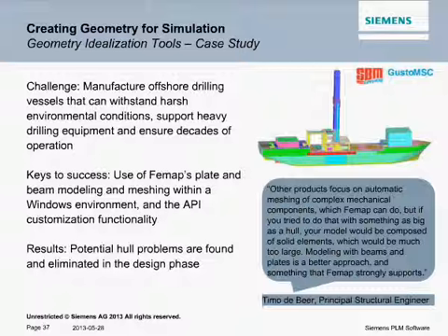Obviously, a ship is a thin-walled structure, and you can get down to extracting these planes and creating a good mesh of 2D elements and 1D elements combined, and get a very accurate finite element model of a very large structure, which will analyze very efficiently.